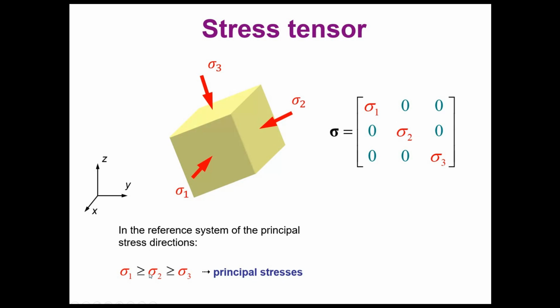And the other thing that you can say as well is that there is certainly an order between these principal stresses, that we usually say that sigma 1 is the greatest, the biggest. But of course, depending on the state of the stresses, all of these can be equal, having a spherical stress tensor, for example, or sigma 2 could be equal to sigma 3, or sigma 1 could be equal to sigma 2 and sigma 3 be smaller, or something like this. So all the combinations are valid.